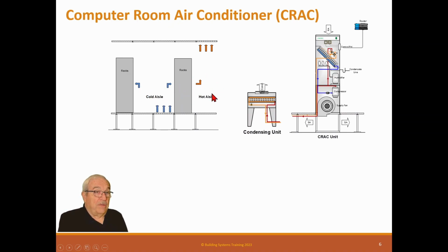So this may now get to be 85, 89 degrees over this side, and this may be 72, 74, 75 degrees. A little more reasonable in the temperature range. There's one other control component that's installed here, and normally we have a water detector, which is a cable that you surround your unit with down here, and it detects if there's any water in this unit. There should not be any water coming down here unless there's a problem.